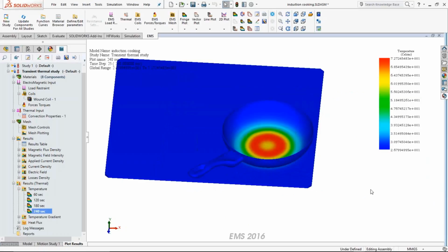So it takes about 4 minutes for us to reach this particular temperature for our design of the coil, and also the current that is input, which is about 8.5 amps. And if you see here, the frequency is about 24 kilohertz. That's around the frequency at which these induction cooktops operate, about 20 to 25 kilohertz. So this is fine.